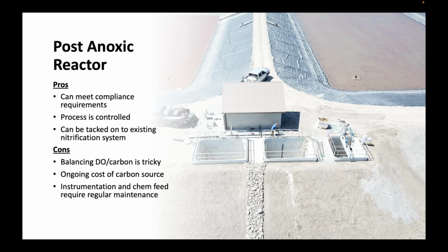You're trying to lower the DO in the denite reactor, and you're adding carbon, and you're trying to maintain a delicate balance between adding enough carbon that you depress the dissolved oxygen, but not adding too much carbon that you end up with BOD flowing downstream that you then have to remove, right? And getting the nitrates to be reduced, right? So I'll perfectly admit that this is a tricky one from an operations standpoint to really maintain.